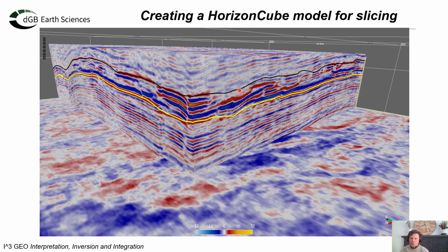For these kinds of difficult horizons, the Inversion Plus Horizon Tracker is an ideal tool, using a hybrid of amplitude tracking and inversion of the seismic dip to track the best horizon. So I can follow well-defined events, like here, where they are present, and bridge difficult areas, like here, based on the seismic dip.